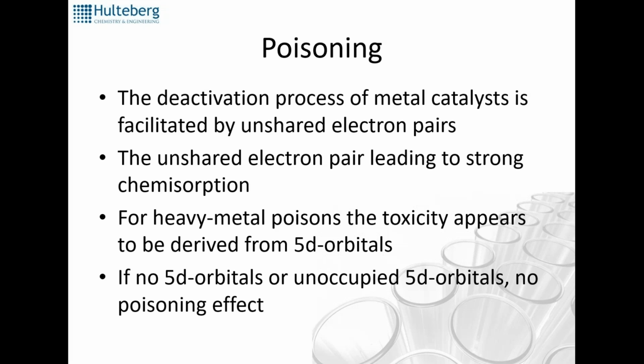So sulfur, for instance, adsorbing on a nickel surface will actually impact not 1 but 8 active sites for steam reforming. So there are effects not only in the closest vicinity but also a bit away from the adsorbed molecule. For heavy metals, it's actually the 5d orbitals that are doing the toxicity. So if there are no 5d orbitals or uncoupled 5d orbitals, there will be no poisoning effect.